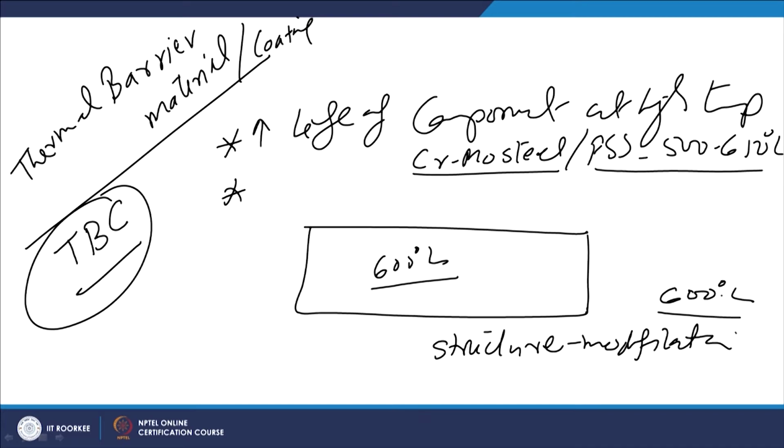In case of steel, it may be in the form of grain coarsening, formation of some kind of carbides, or depletion of some of the alloying elements from the functional surfaces. These undesired structural modifications lower their mechanical properties.